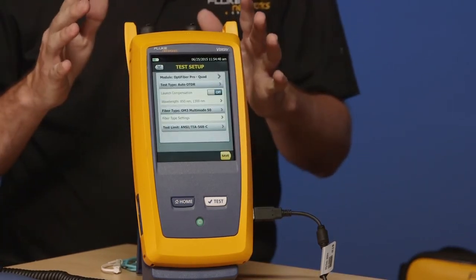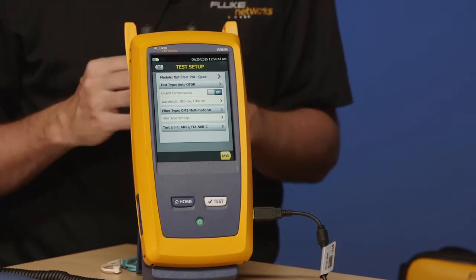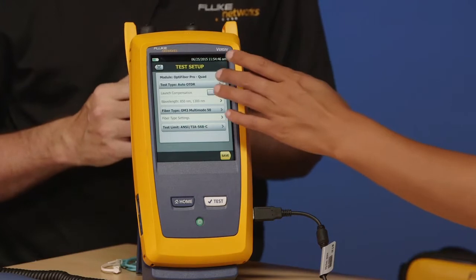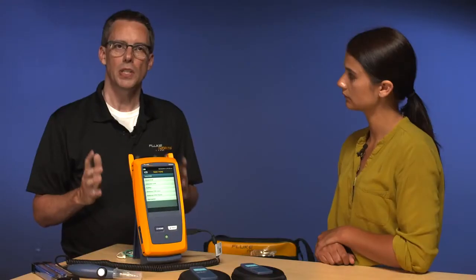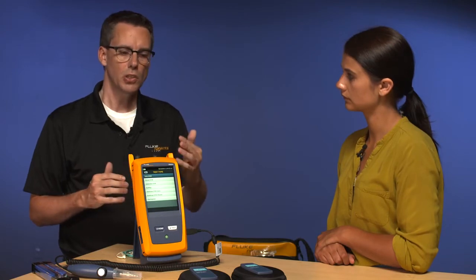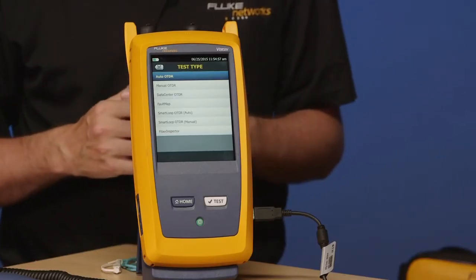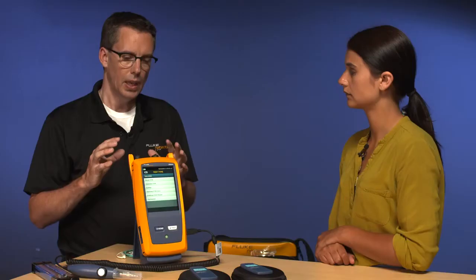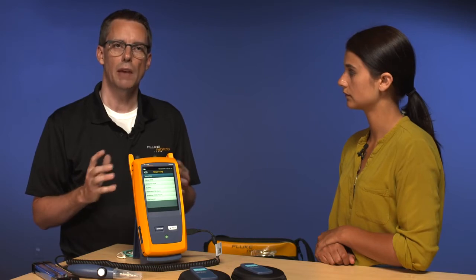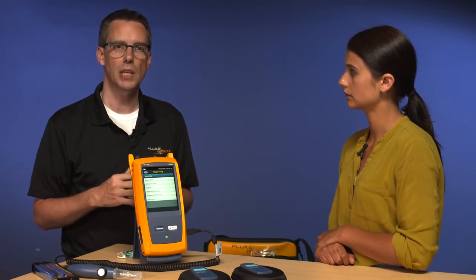So the first thing on there is the type of OTDR test. And there are a number of options here. So go ahead and tap on test type for me. We're not going to do all of these today, this is just a getting started video. The first option on here is Auto OTDR, which is one of the most common settings. The reason why is if you leave it in Auto OTDR mode, it will decide what the pulse width, the averaging, and all the ranging, and all the other stuff that you typically manually have to set up.